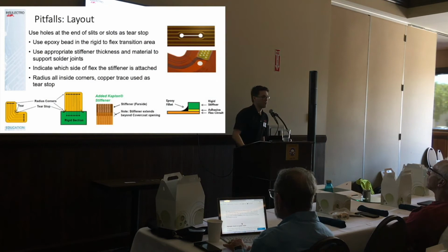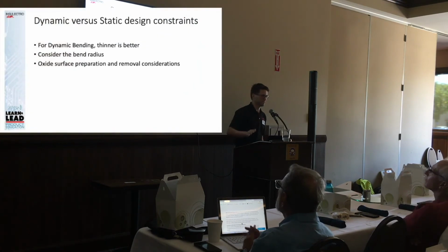The other thing that we can look at is if we have to bend a flex cable beyond what we normally would consider, we can put stress reliefs in them, and we can drill and cut slots in our flex cables where we know there's going to be stress concentration factors. We can cut it out and eliminate a lot of the stress that may be unduly applied to our flex cable. So hopefully you all mastered that information and you're now flex experts for design layout.